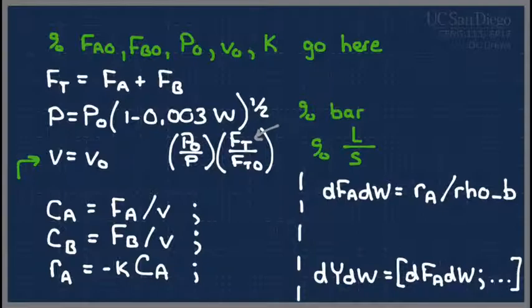Do that for your projects. You don't want to try to do it in terms of conversion. Well, you can't do it in terms of conversion because it's a multi-reaction system anyway. So what we'll do is revisit this particular problem as we develop our energy balance, and we'll add additional terms to it. We'll keep the pressure in there. By the time we're done, we'll have a single reaction with pressure drop and with thermal effects, with a jacketed reactor going either way on the jacket. And so this will look like a miniature project.